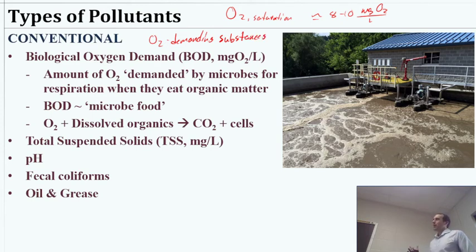And this is then a kind of a catch-all term for anything that bacteria can consume, and in doing so, for an energy source, essentially, to perform respiration, breathing in and out for these bacteria. So that amount of oxygen demanded is what we're measuring specifically, and it is capturing a catch-all for bacterial food in that regard. Okay, so that's our term.